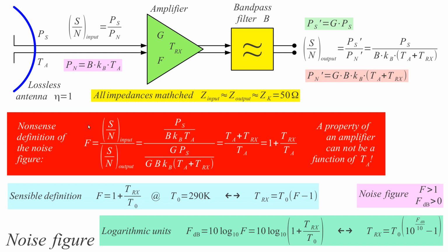They were not calculating the signal to noise ratio, but they were calculating things against a lossy cable, or against an antenna pointed to the ground, or against a signal generator. A signal generator also has an attenuator on its output, and it is radiating noise at room temperature. So this sensible definition also applies when we are using signal generators, say, to check our receivers.